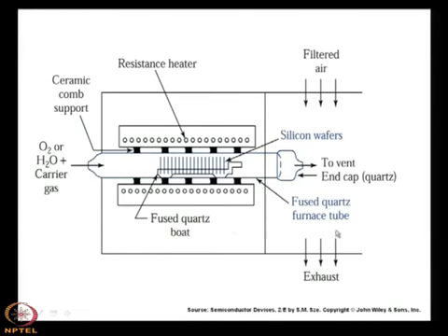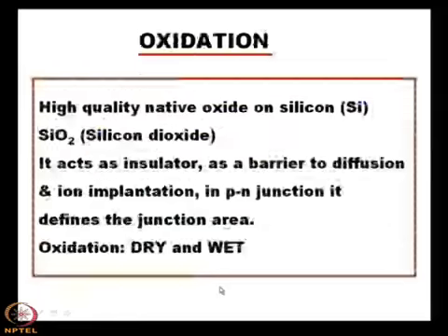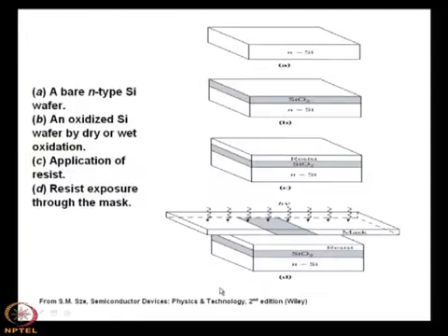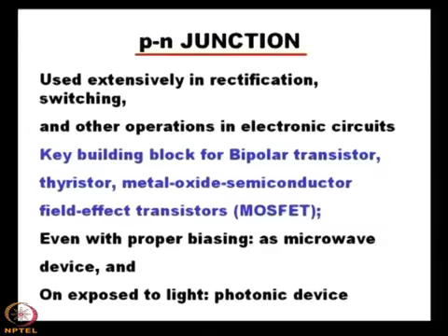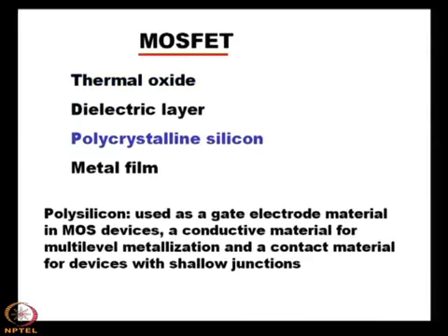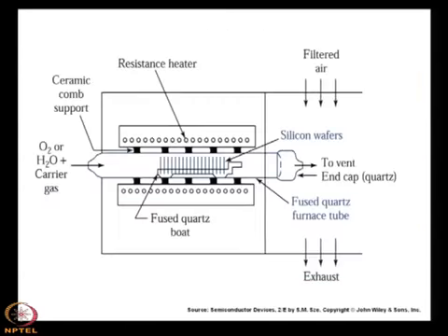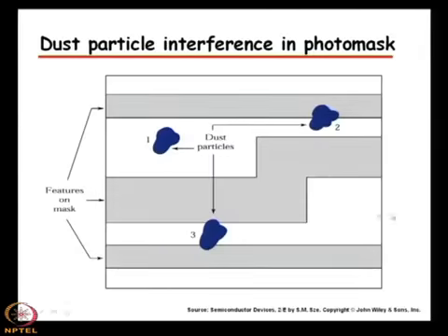So, this is the standard protocol that we have used, and obviously, we have discussed that this must be accompanied by the clean room, because without a clean room one cannot make this oxidation very good. Otherwise, there will be a large number of dust particles that will have their own imprint or signature on the wafer surfaces in the later stage.